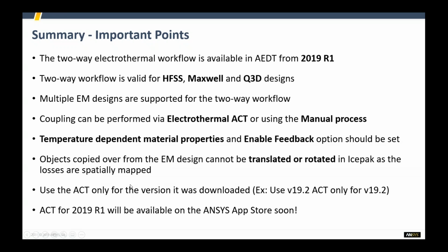If you want to do a thermal analysis, use the ACT only for the version it was downloaded. So just pay attention to the version. At this point, I believe 2019 R2 is available also. So ignore the last point.